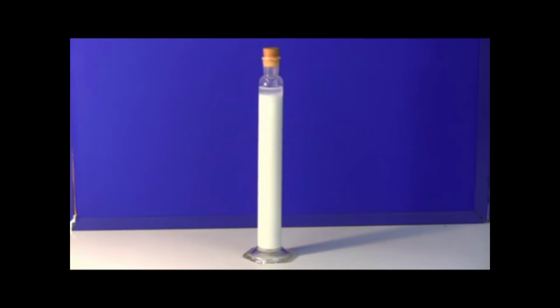And here is some sedimentation. This is a fairly fast sedimentation. It's normally a much slower process than this, and typically performed in batch jars like this, measuring cylinders like this. The good news from the design point of view is that the sedimentation rate is not dependent on the vessel area. So laboratory tests using measuring cylinders are very good for designing industrial thickeners much bigger. That's industrial devices much bigger in area for separations.